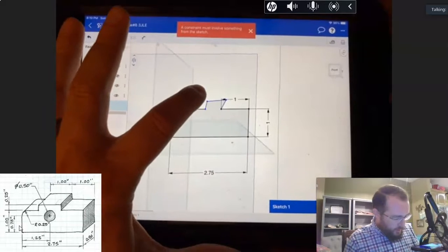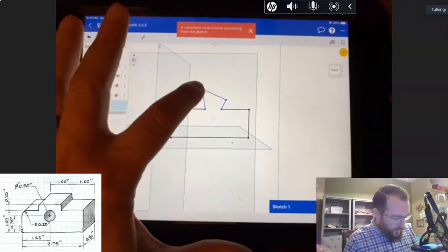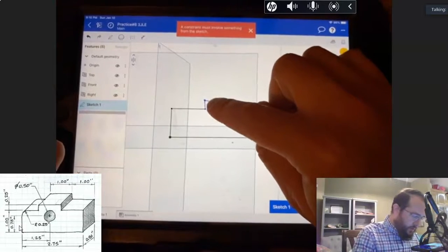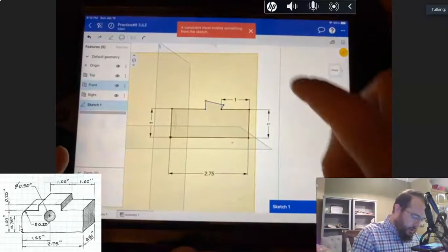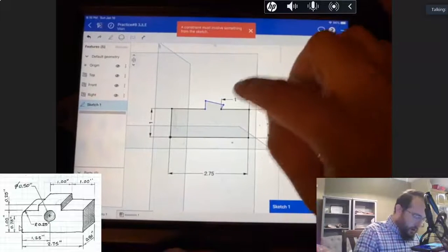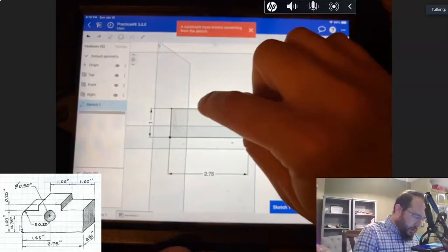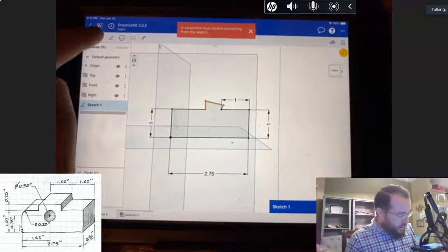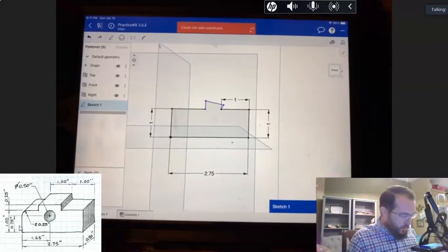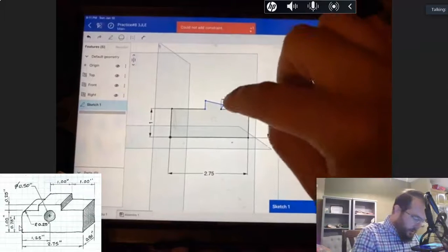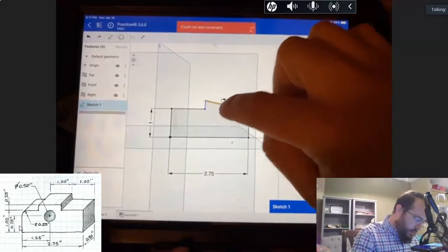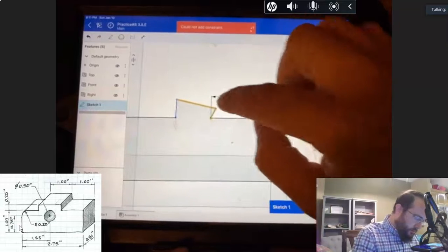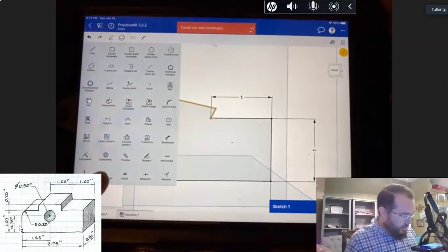If you look at the blue stuff, I can click on that and I can move those around. I can still have control over those, and I don't like what's going on there. So I'm going to stop selecting everything. Click on 2 of these here, 2 points, and I'm going to click the line tool and say perpendicular. I want those to be perpendicular. And click on 2 more and say that those also need to be perpendicular.